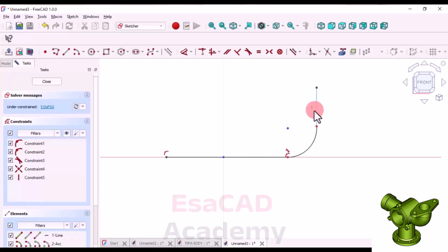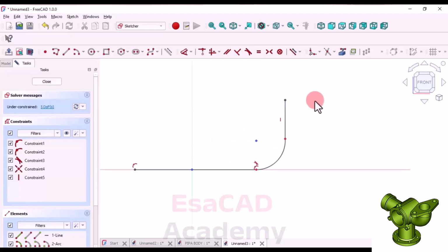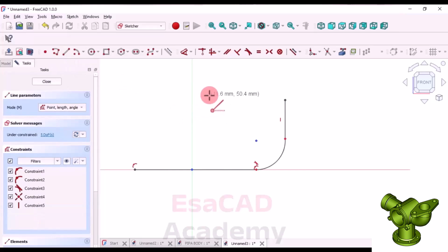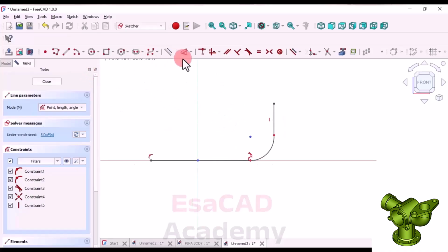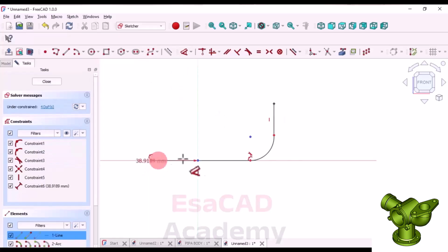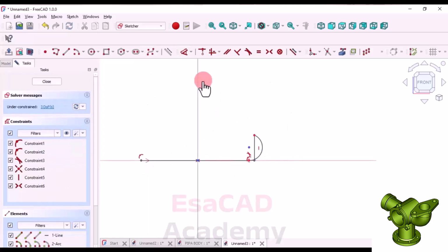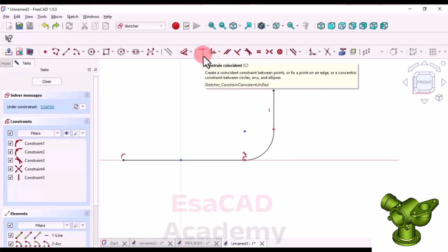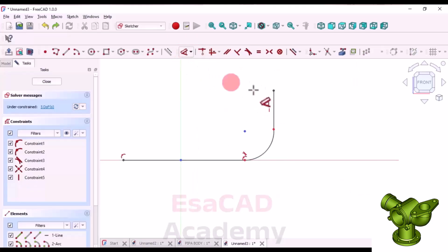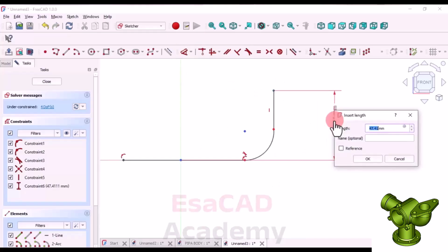Please right click now. We need to repeat the escape action by right clicking on the mouse, which will cancel the current cursor selection, and then, after successfully cancelling, we will proceed to create the dimension for our design. The distance between this point and that point. Let's repeat by pressing Ctrl Z. Move to this point here and set the value to 70.